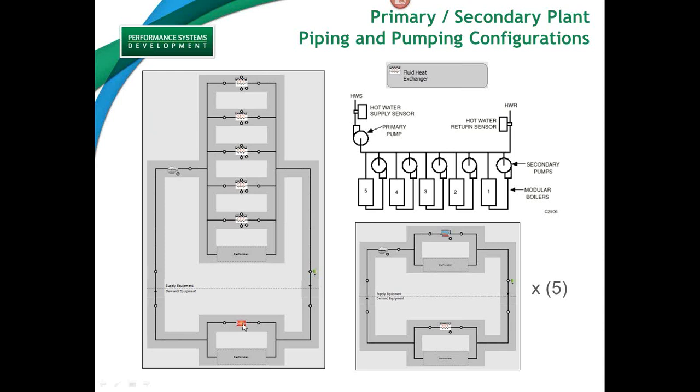So in this case, to keep the image small, I just had 1 load, but you could have many, many loads. OpenStudio is very flexible in its configuration for primary and secondary pumps. You can have as many primary loops as you need, as many secondary loops, multiple secondary, and even tertiary pumping. So that's a very powerful feature, again, for modeling real-world systems, whether they be hot water, as this example, or chilled water, or perhaps even condenser water.